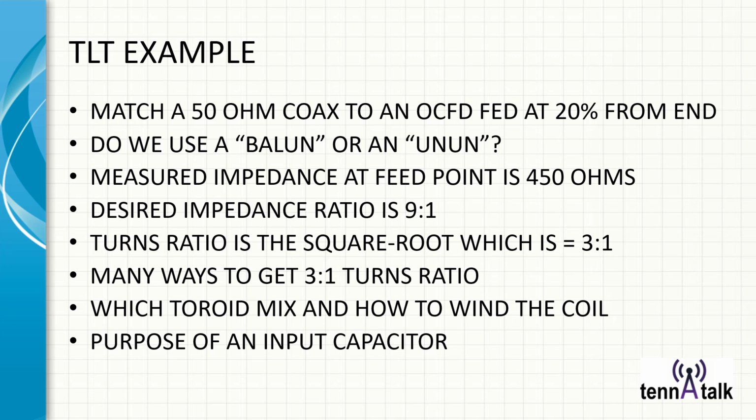toroid mix 43, and we'll learn how to wind that coil in the Part B section of these presentations, which is the workshop section. And the purpose of an input capacitor is to help bring down the reactance that is part of a TLT in the system.